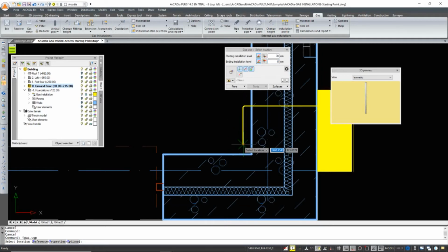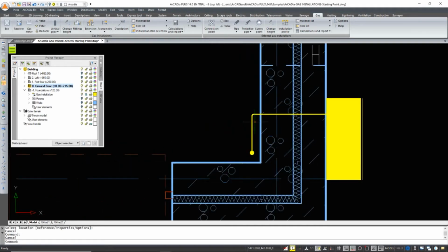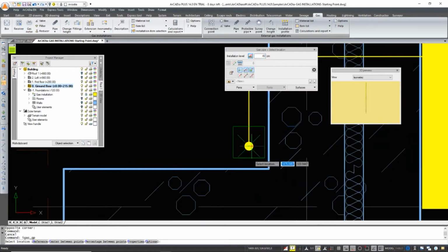The program will search from 0 to the nearest point of the pipeline, then the other free end under the ceiling at a height of 240 centimeters. And this is how the vertical pipe is made. Next, the horizontal pipeline. We also import the height, but here we enter the expected value greater than our top vertex, about, let's say, 345 centimeters.